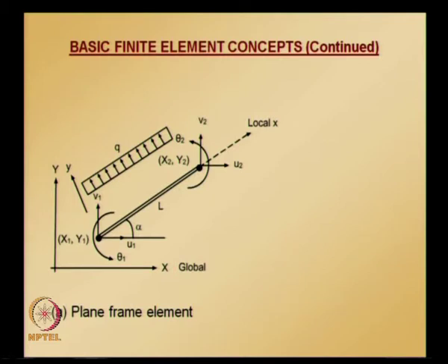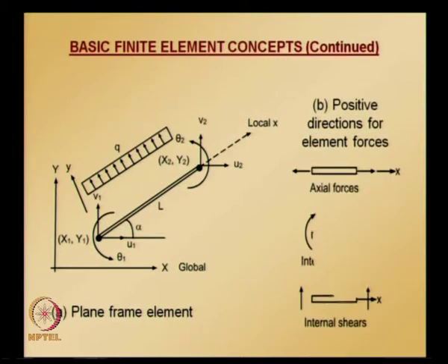Positive directions for internal forces, moments and shears are shown here, and the sign convention is similar to what we adopted for beam element and also what we adopted for axial deformation elements. So, the same sign convention is carried forward, because basically what we are doing is assembling the element equations for a frame element based on element equations for axial deformation element and bending element.